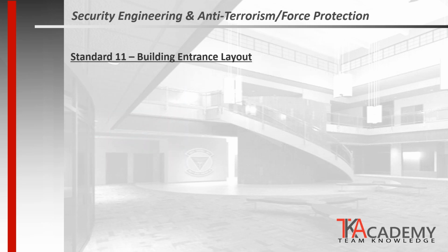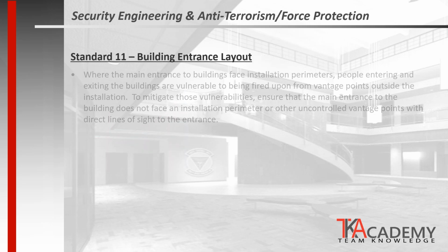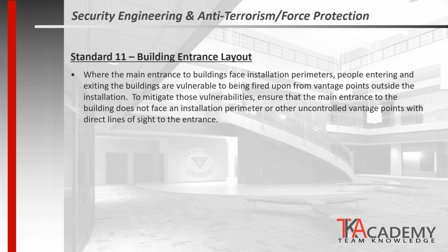Standard 11 applies to building entrance layout. It states that when a main entrance of a building faces an installation perimeter, people entering and exiting the building are vulnerable to being fired upon from vantage points outside the installation perimeter. To mitigate those vulnerabilities, the design should ensure that the main entrance of the building does not face an installation perimeter or other uncontrolled vantage points that have direct lines of sight to the entrance.